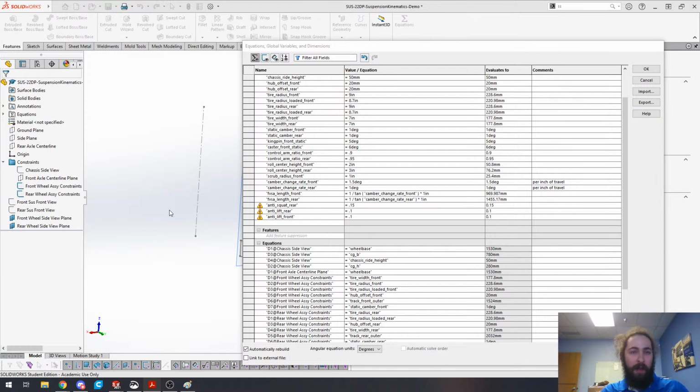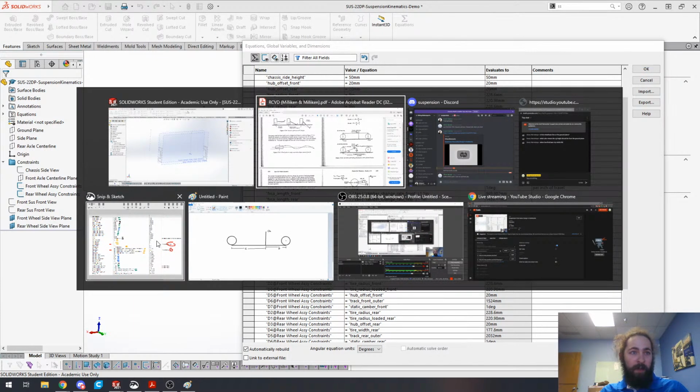Okay, so anti-dive, basically in that section it goes through some of these forces are evaluated at the ground, and some of these forces are evaluated at the wheel center line. And based on pairing those two up, we can just have two angles, one of them evaluated at the front wheel center point where it contacts the ground, and also from its center line where those two lines intersect. That's our side view instant center. We'll kind of build that up here. But first we have to calculate those angles.